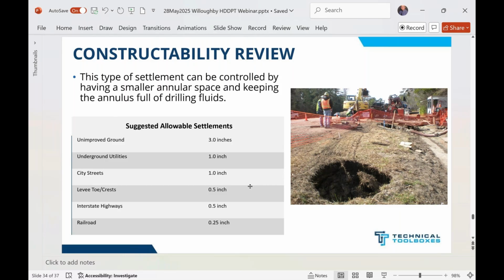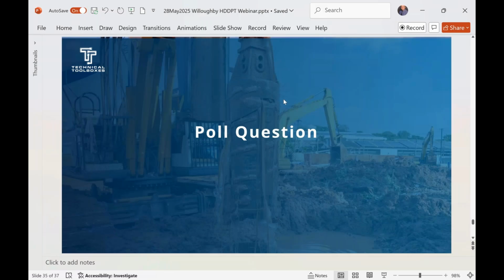If you encounter any underground clashes? Yes, sir. So I guess related to the power tool, if they have some type of underground barrier or clash, can we avoid that along the drill profile, steering left or right? Well, if you have room to avoid it, assuming you know it's there when you do your layout, you could avoid it. Now, if you're doing drilling and you don't know it till you hit it, of course, then that's too late.